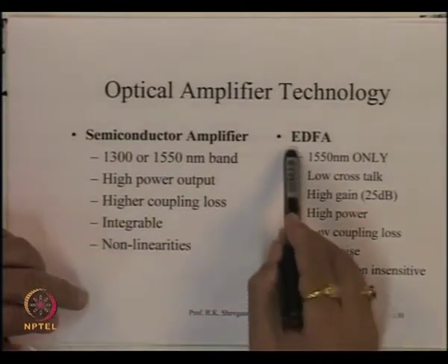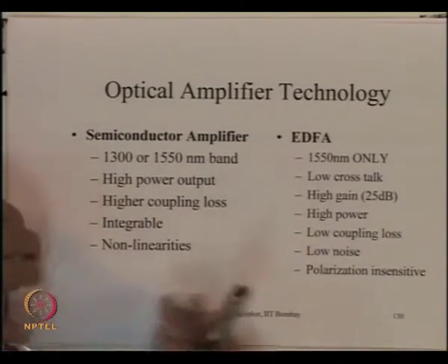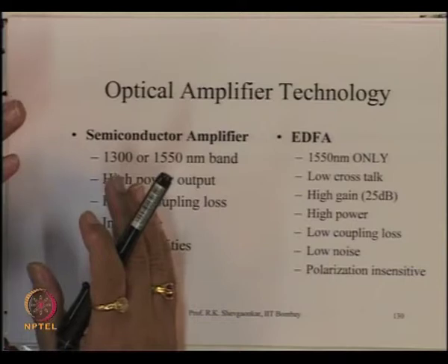So the EDFA essentially offers many more advantages over the conventional semiconductor optical amplifier, and that is the reason this amplifier has gained popularity over the last one decade. The only limitation we see for this amplifier is that it has to work only in the 1550 nanometer window.